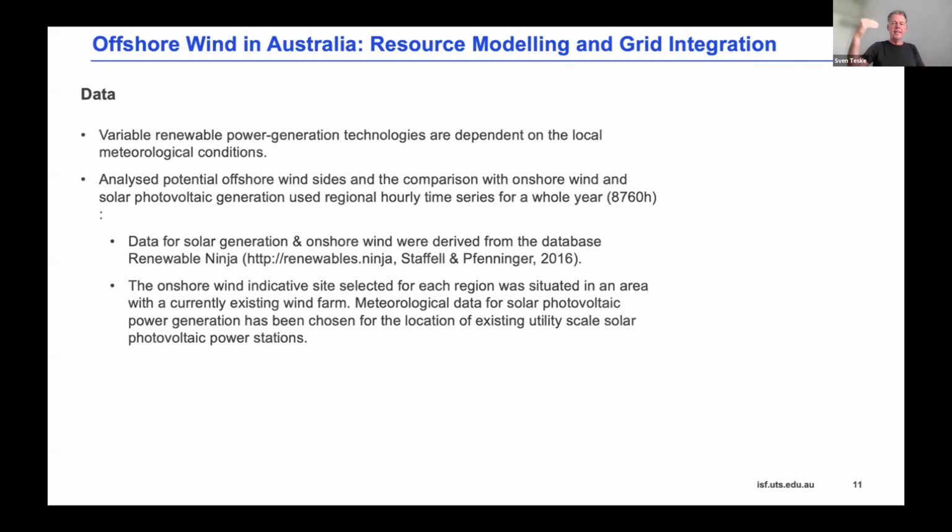So you have to have an interpolation, which adds a very high uncertainty, usually in the positive space, as the same happened in Germany 20 years ago. Then they installed an actual wind mast in the North Sea and realized that the wind was like 30 or 40% stronger than they expected. So basically, there is an uncertainty about the offshore wind measurement, as there is no actual measurement.